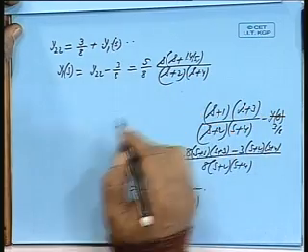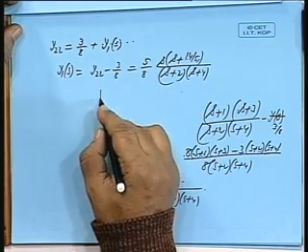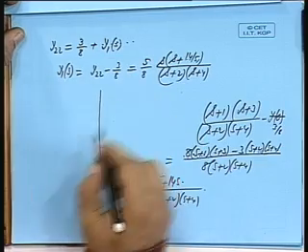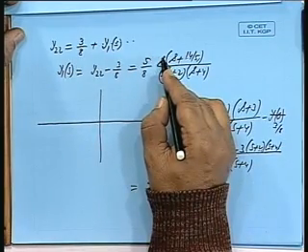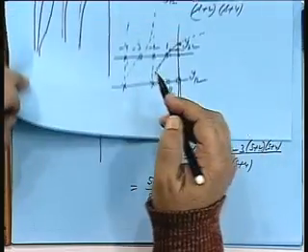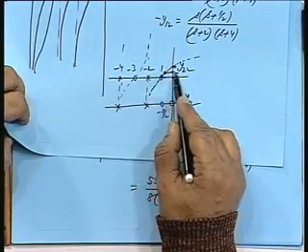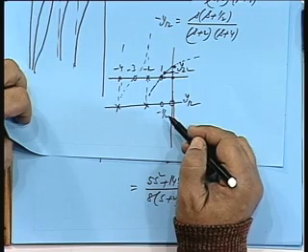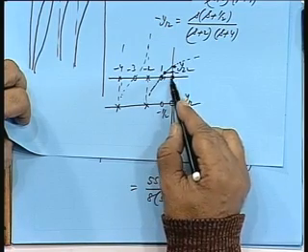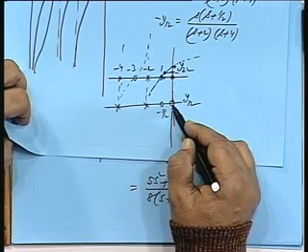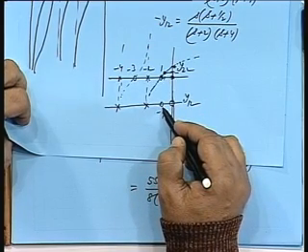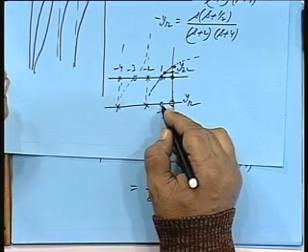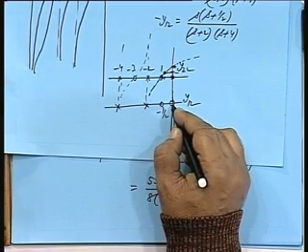So, what would be the zeros for this y1s? I have realized one 0. I have removed it completely. So, if I remove it completely, this will be hitting here only, is it not? So, I will get a 0 here, and that is one of the desired zeros. I could have realized partly and got into this 0. Okay. Either you realize this 0 first or this 0 first, you take one at a time.